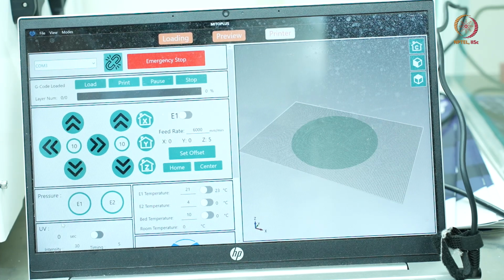What many people do is add Irgacure or LAP, which is used as a photo cross-linker, along with the hydrogel, and they print this gel. After they print it, they use UV cross-linking operations. Or they can use chemical cross-linking by using calcium chloride. This calcium chloride cross-linking is also another useful route for cross-linking of hydrogel scaffolds.